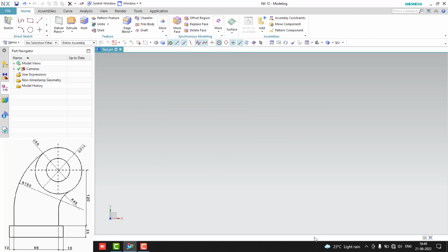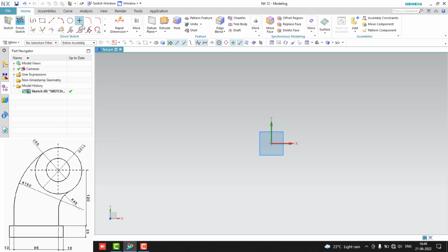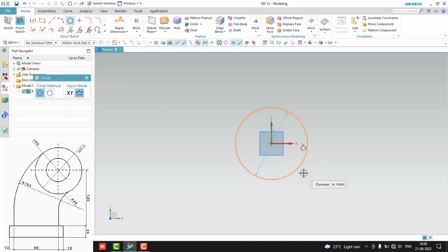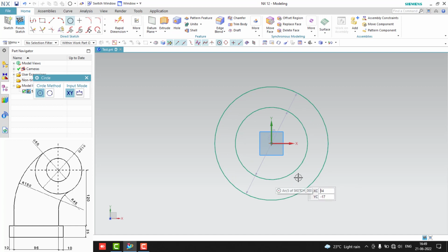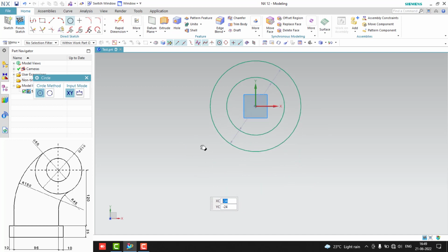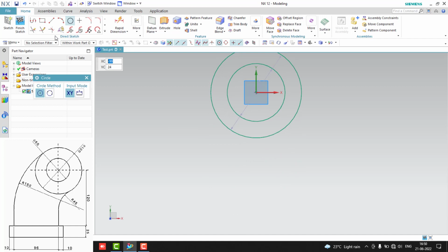You could see the sketch. So for this I'll start with the origin. Okay, so I can use the circle at the center and I'll start the circles, and then I'll draw the remaining. Auto dimensioning I'll turn off because it will create errors. So next thing, I just need to draw the lines and the rectangle and then later arcs. So first let me just draw the rectangle.